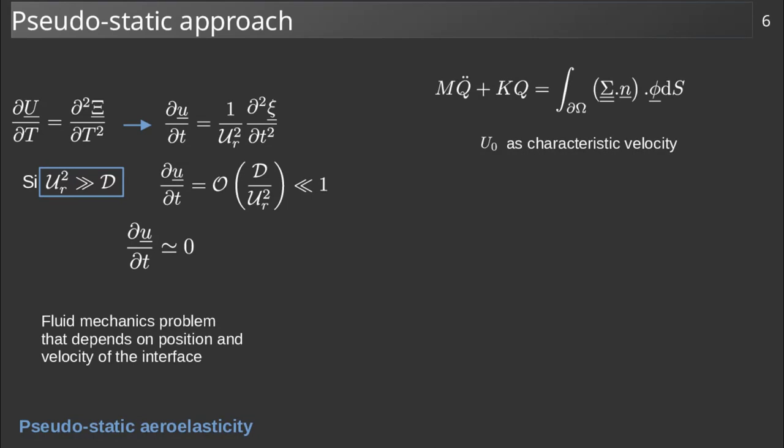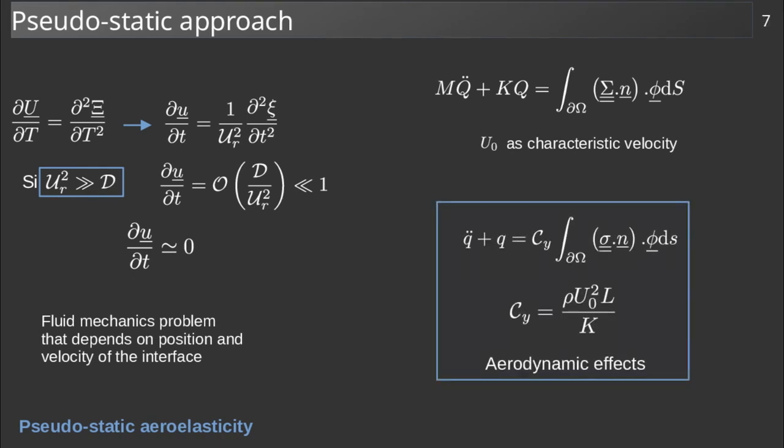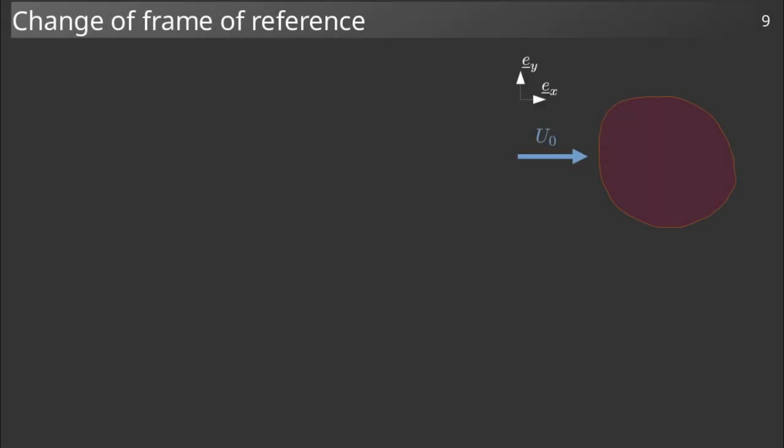If we transfer this to an oscillator equation describing the dynamics of the structure according to a mode, and we scale this, we obtain a force equal to the product of the Cauchy number and the fluid stress projected on the mode. In view of the preceding discussion, this projected stress is in this approximation framework a function of Q and Q dot. Let's see this in the case of a profile with any shape in a flow at velocity u0 animated by a solid body motion.